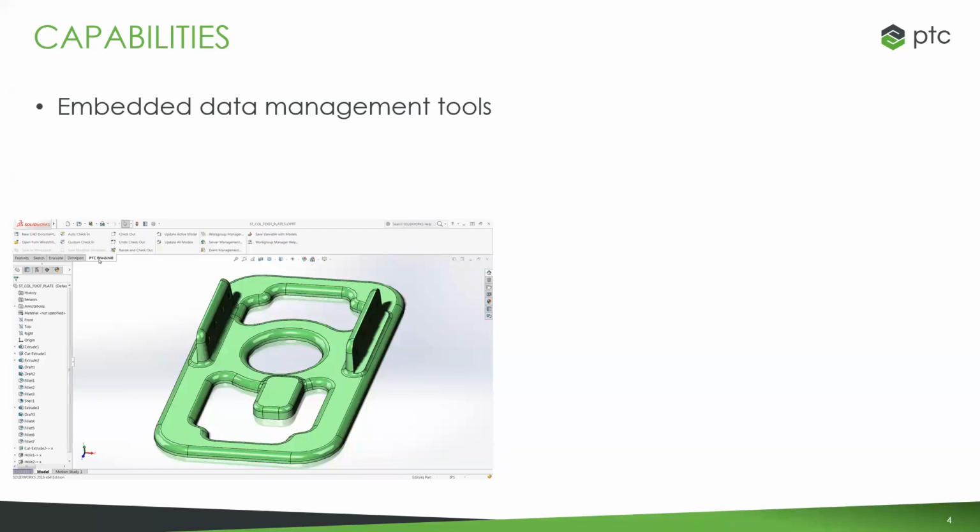Designers are comfortable working in the CAD system. So this is giving them a way to just continue to work in what they're comfortable with. They don't have to be a Windchill guru to open up the Windchill tab in SolidWorks and check something in or check something out or do a save as, or even undo a checkout if you did something accidentally and want to reverse it, right? You're doing it all in SolidWorks. It's the tool that you're familiar with. And it's all seamlessly integrated.